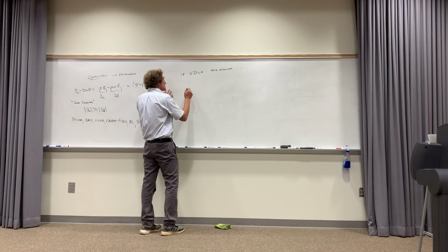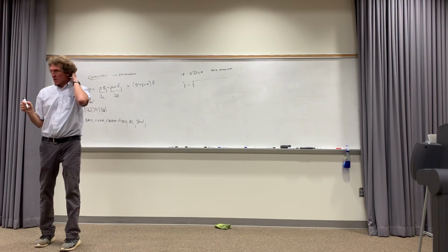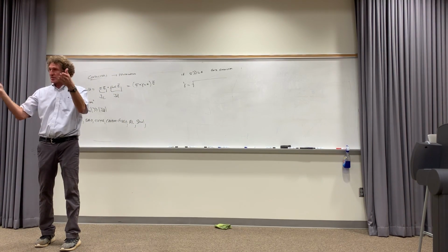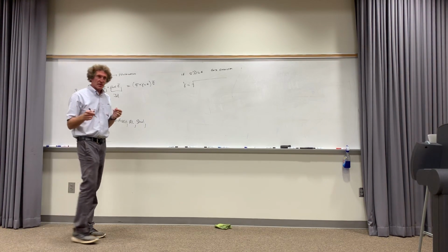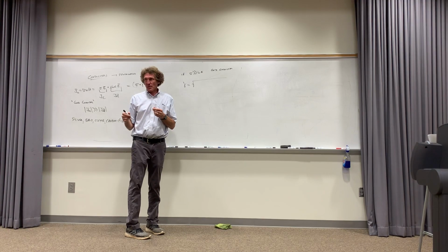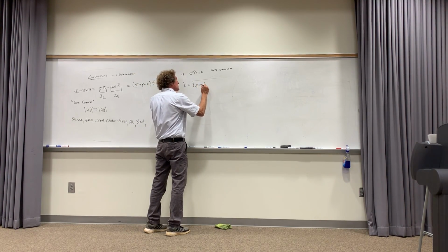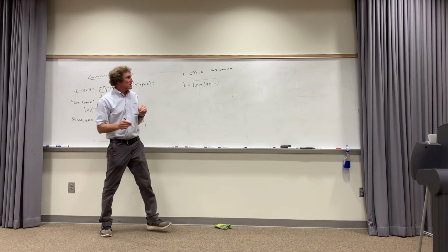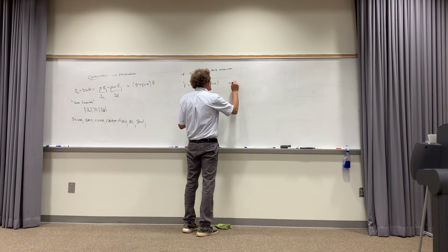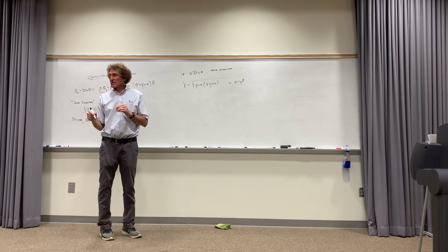So if it's a good conductor, when you look at things like the propagation constant, do you remember what the propagation constant is, people? This is for intrinsic media, for a medium. Anybody remember? We developed it. When we did it, what did we say? It was the square root of J omega mu times sigma plus J omega epsilon, didn't we? And that was equal to alpha plus J beta. This is very important. That's the propagation constant, right?